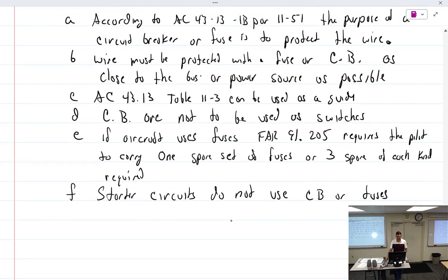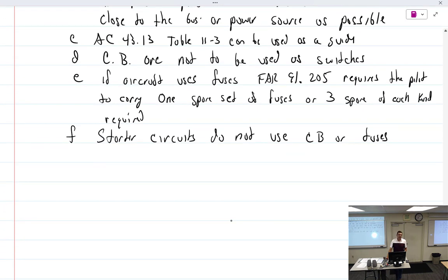Directly to the battery, right? No, actually you have a fat wire that goes from the battery, not to the bus bar, to the master solenoid. So when you hit the switch, the solenoid closes, then that goes to the bus bar, but that fat wire is right there at the relay. And then there's another relay that sits usually right next to it, especially in Cessnas, sometimes with just a metal strap going across it.